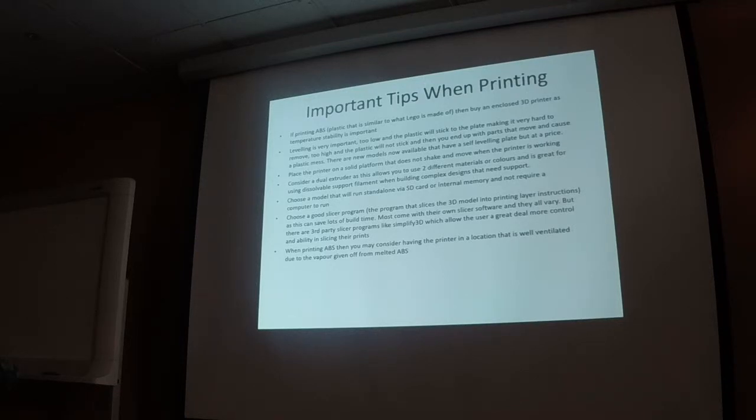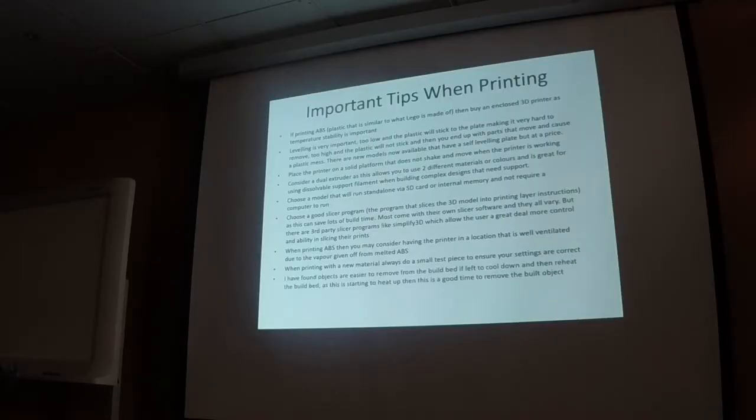When printing ABS, you might consider having the printer in a location that is well ventilated, because ABS does let off a bit of an odour when it's been extruded. PLA doesn't let off as much odour, but you'll definitely notice it. So I have mine sitting in my garage because I don't want the house smelling of plastic. When printing a new material, always do a small test piece to ensure your settings are correct.